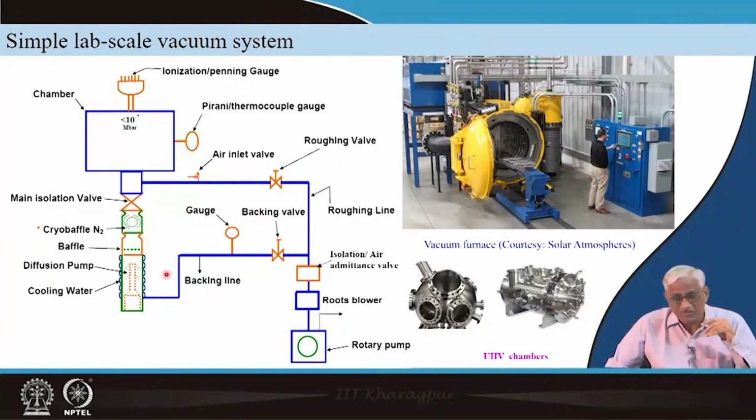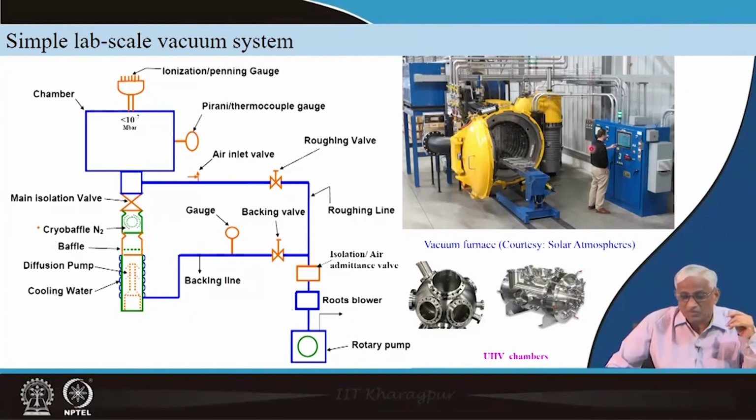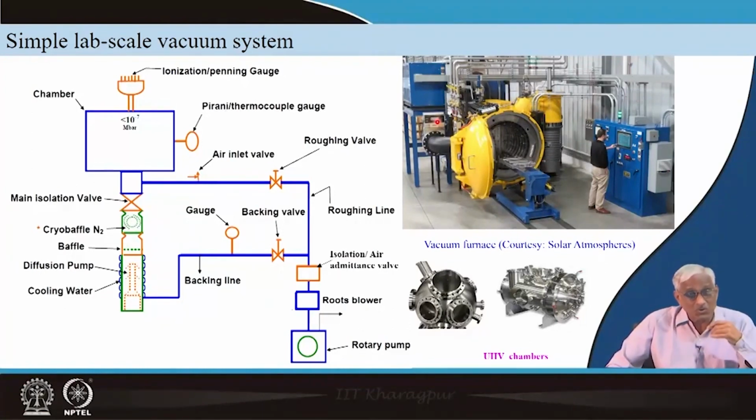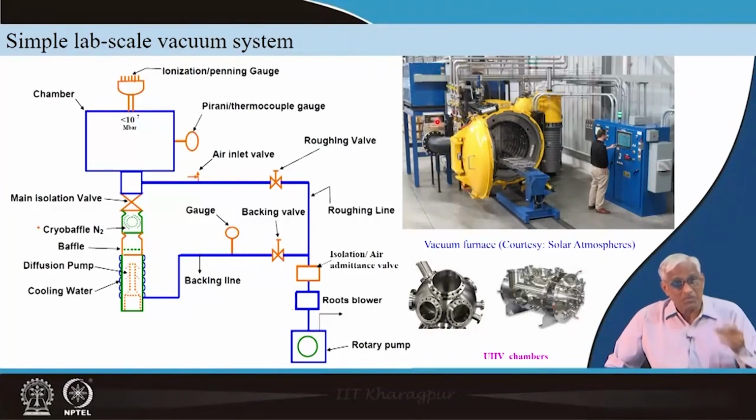Similar systems we will be facing when we are dealing with a vacuum metallurgical furnace. You can do a 1-to-1 correspondence here. This is the system, this is the system. These are gauges, valves. Similarly, pumps, diffusion pump. Backside there will be a rotary pump, roots blower, but with a bypass connection, because for initial evacuation you have to use the roots blower to boost the pumping, and then later you switch it off, otherwise there is a lot of electrical power requirement.